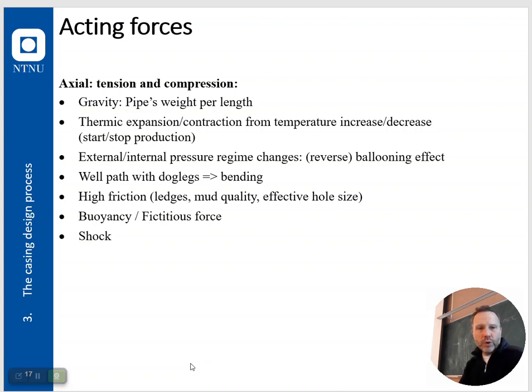That drawing is going to come where we're seeing a pressure test of the annulus, how it squeezes the pipe and it becomes thin. The OD reduces and it elongates. That's the natural state of the reverse ballooning, and the opposite for ballooning.